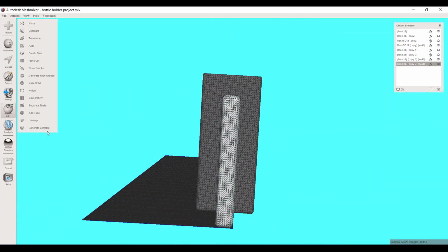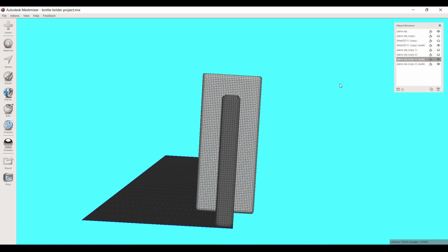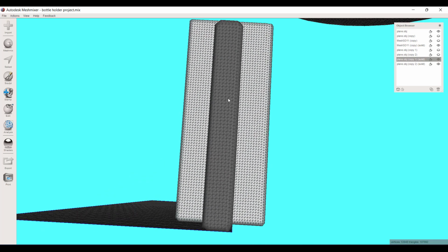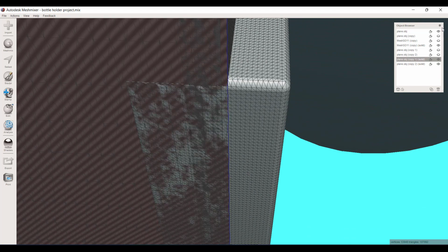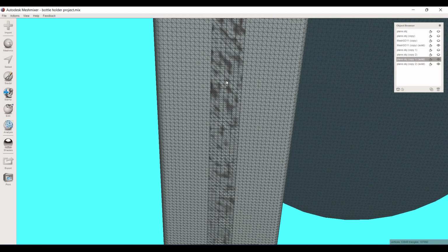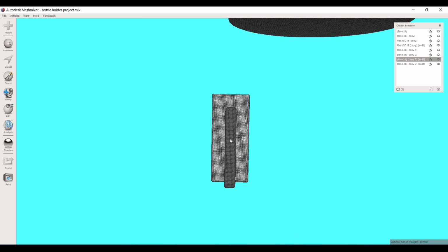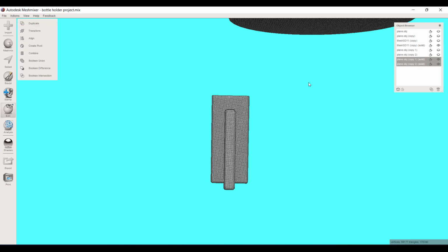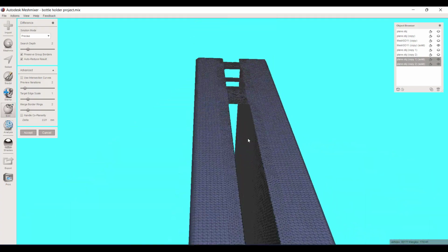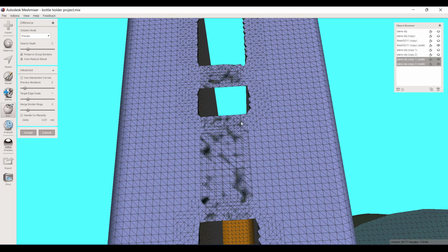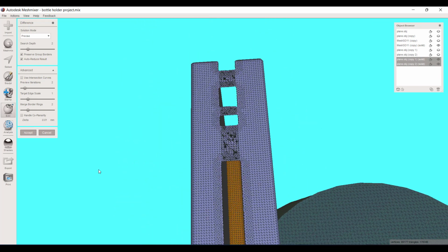All right. Now the one thing that could be problematic is, and I'm going to Control S in case this crashes, but this is a good learning opportunity. What if I just take this shape and subtract it from this shape? Now, mind you, if I look at the bottom, these basically share the exact same bottom edge. All right, watch what happens when I attempt that. So this, control select that, the object you want to subtract, and do Boolean difference. All right, now I'm actually surprised it worked, but it didn't work completely, right? Because those meshes were so similar, it doesn't know how to subdivide those triangles.